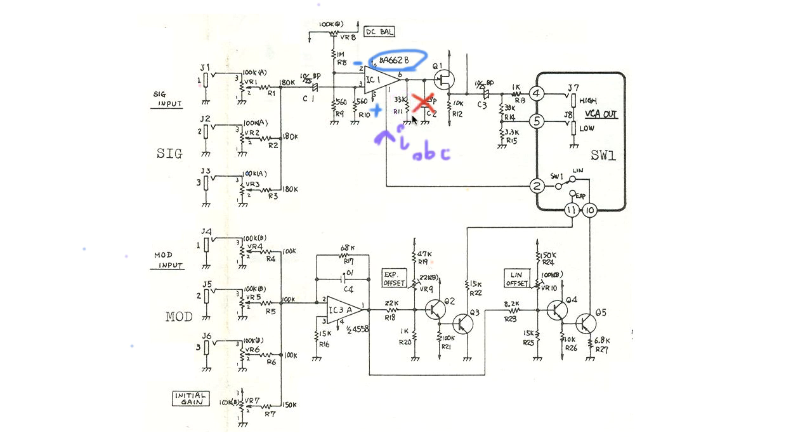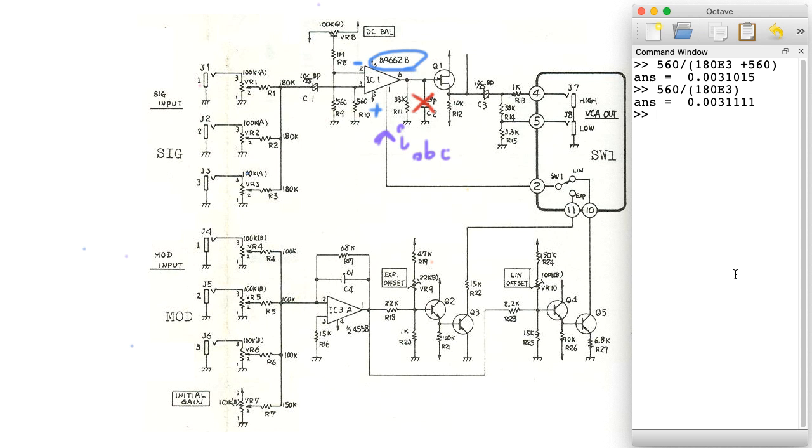All right, so let's go back to Octave. We have this attenuation factor of 0.003 something. I'm just going to truncate it there, times whatever the transconductance gain of the OTA is. So that's going to be 19.2 times this control current, or what did I call it? I said IABC. So that's our control current. So just keep track of the fact that there's this control current number sitting there in your head, and we'll put it back in later.